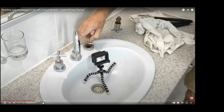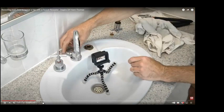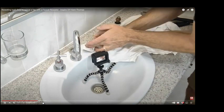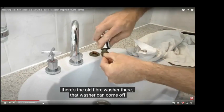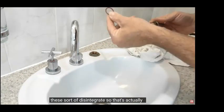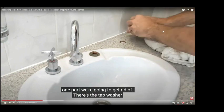Yeah, so basically you pull the tap body apart. Usually you take the handle off first, however that comes off. So a basic Methven Coffi tap, which is quite common. There's a little cap. You take the cap off, you undo the screw. You then take the handle off. Then you unscrew the shiny chrome cover piece, which he's still left on there.